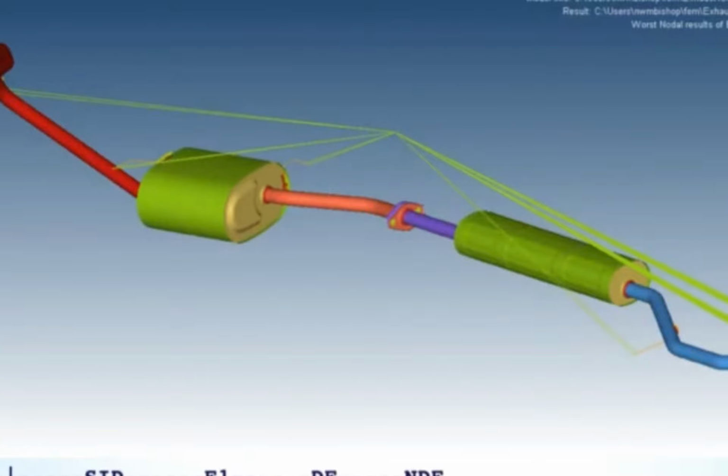the positions where you're going to request frequencies. So in this particular analysis, the person that set this up requested Freq 1 and Freq 4 cards. I don't know if you're familiar with those, but Freq 1 is a way of equally spacing points at set intervals. So the first line is a Freq 1 saying, please put points from 0.1 hertz, 25 of them at 2 hertz intervals. The second Freq 1 says start at 50 hertz and put 22 points with 20 hertz intervals. And then the next line, the Freq 4, says put points around each resonant mode, and the NFM, number of frequency points, is 3, so put 3 points round every resonance.